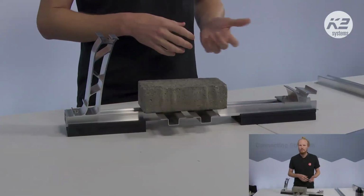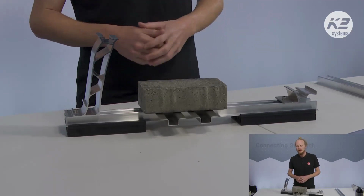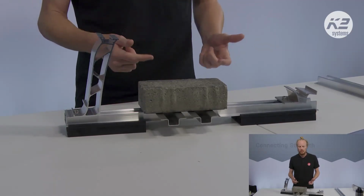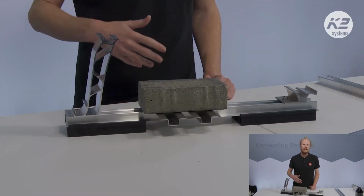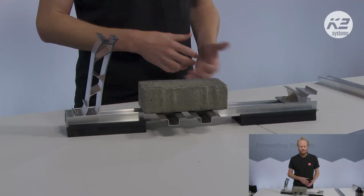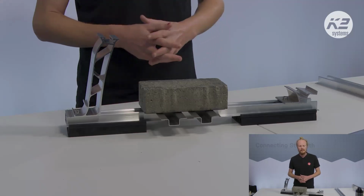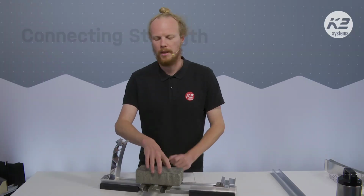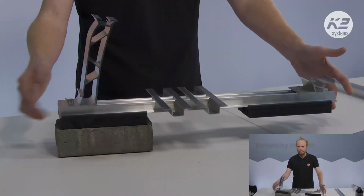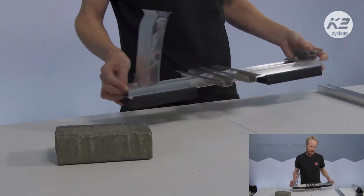So when you have gravel roofs or green roofs, you already have this excess weight on top of the building. It's not necessary that we need to then put on extra ballast if we can somehow use that additional weight. And so one of the systems we have goes through this and sort of using the weight, and the other one is a little bit different, where instead of putting the ballast on top, we put the ballast sort of underneath and screw the rail on top of that. So this is our express system, so it's not sort of the best example, but just to give you an idea.